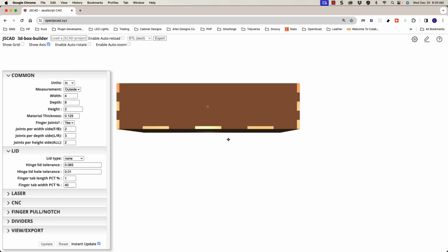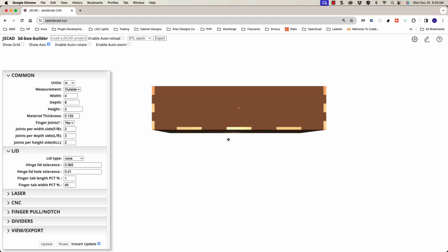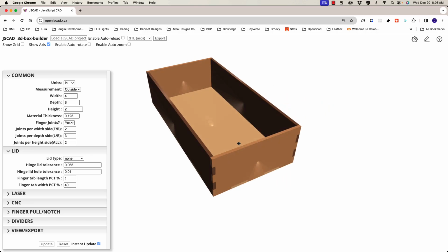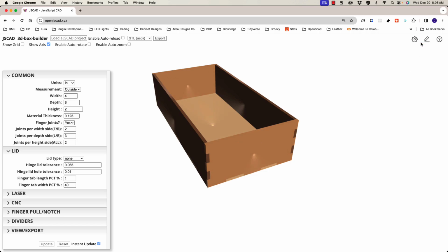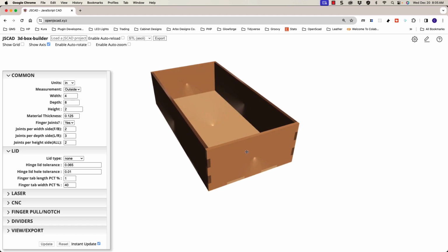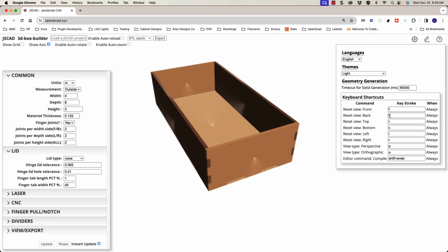You can do left view L, right view, and then the front and back are reversed, so you're going to have to hit the B key to get the front. I think JSCAD has those backwards, based on how I program the XY axis. So just be aware that those are reversed, or you can come over here and change those if you'd like.